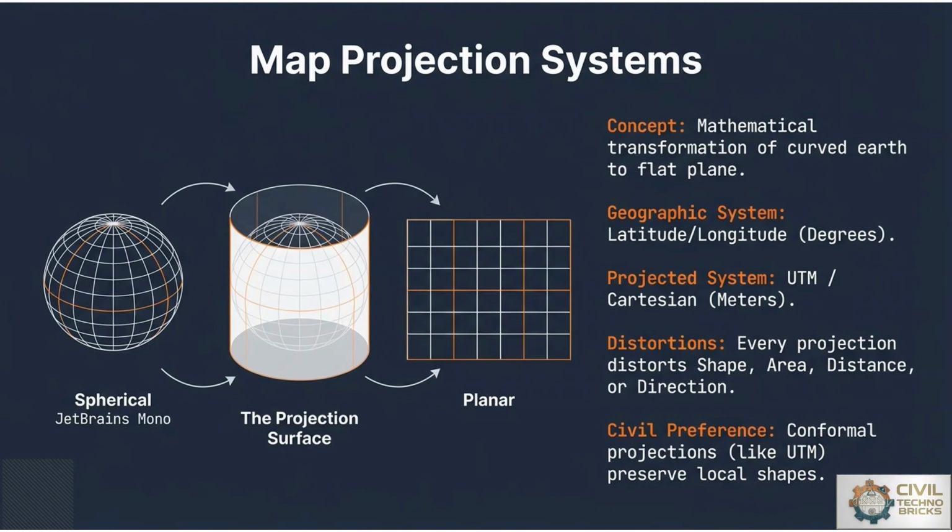So this whole cylindrical earth is converted into a plane, and that geographic system shows the latitude and longitude in terms of degrees, minutes, and seconds, so that we can take the ground control points for our reference and for our updating procedure. The Universal Transverse Mercator or the Cartesian coordinate system, which is in meters, is used as the projected system for map projection.